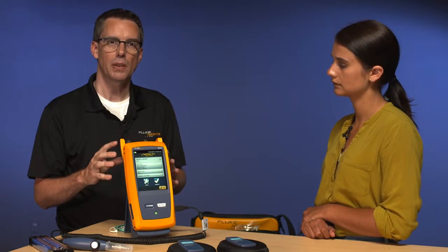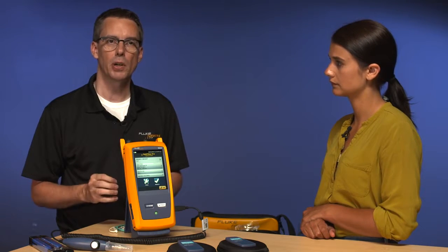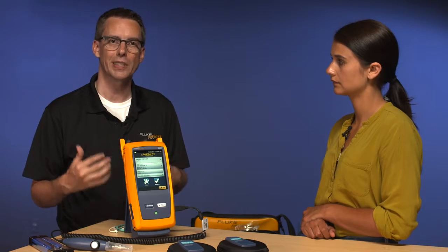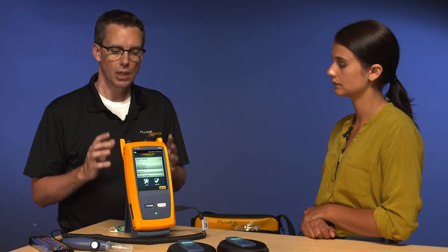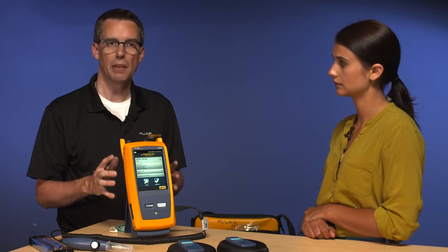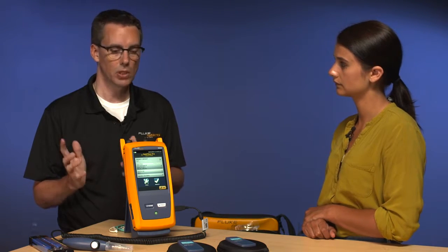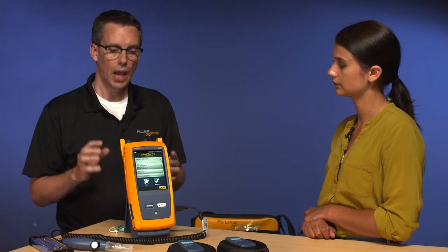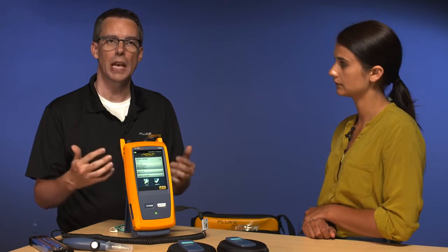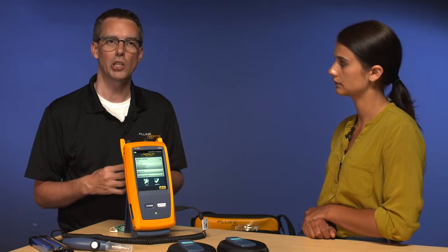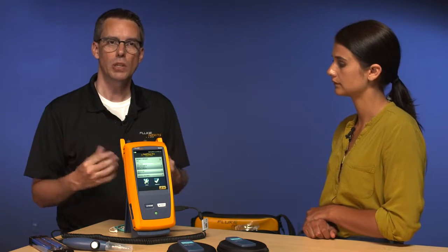So what's great about the Versiv platform and this OptiFiber Pro is I can create up to 100 projects in advance within the tester. So when this tester leaves here today in Everett and I go to, say, Edmonds, which I'm going to go to in a moment, I can simply change the project across to Edmonds and I get my test configuration and my cable IDs for Edmonds. So let's create a project.